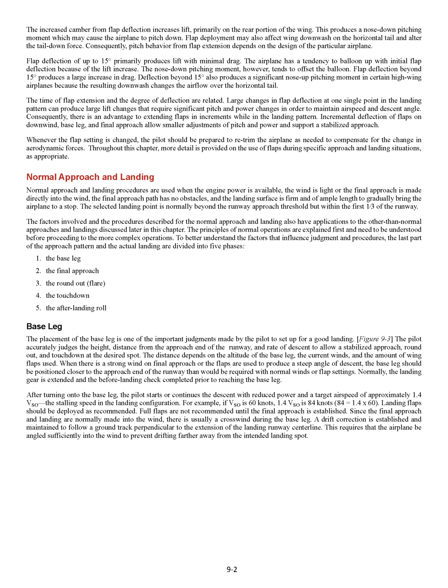Consequently, there is an advantage to extending flaps in increments while in the landing pattern. Incremental deflection of flaps on downwind, base leg, and final approach allows smaller adjustments of pitch and power and supports a stabilized approach. Whenever the flap setting is changed, the pilot should be prepared to retrim the airplane as needed to compensate for the change in aerodynamic forces. Throughout this chapter, more detail is provided on the use of flaps during specific approach and landing situations, as appropriate.